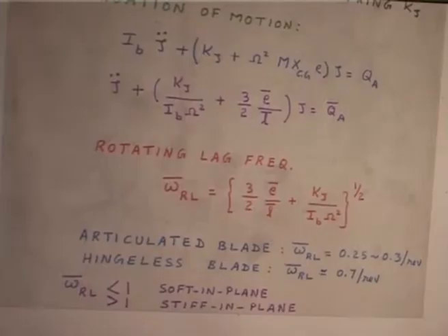That means the coupling of lag with respect to flap motion or with respect to fuselage motion, they can lead to instabilities. Okay. Isolated lag is fine, that means just pure lag motion, it is stable, because the damping is, of course, purely aerodynamic damping in this case. We have not put any external damper there.